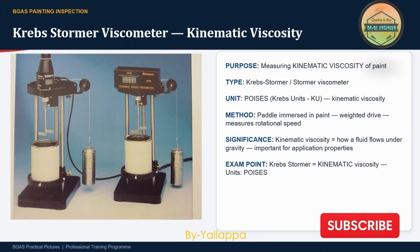This slide shows the Krebs Stormer Viscometer. The instrument measures paint viscosity using Krebs units. This method is commonly used in paint manufacturing and laboratory environments. Understanding viscosity measurement techniques helps inspectors verify that coatings meet manufacturer requirements before application.